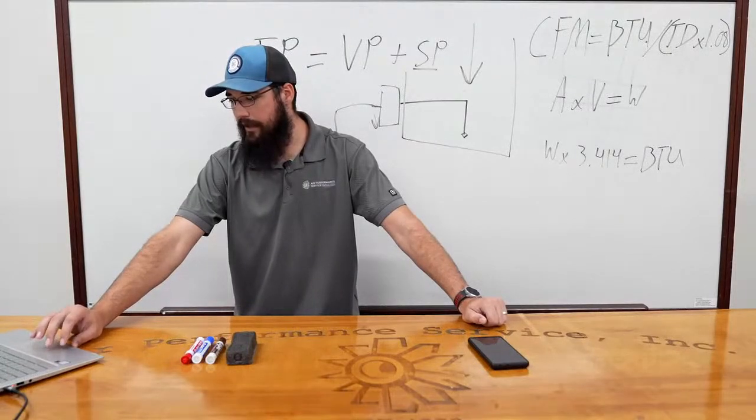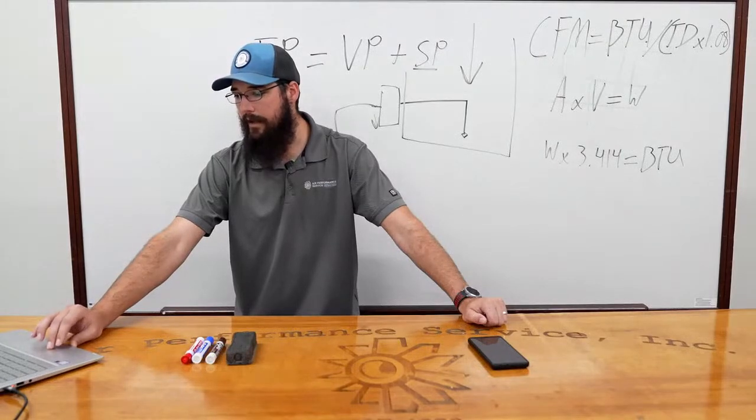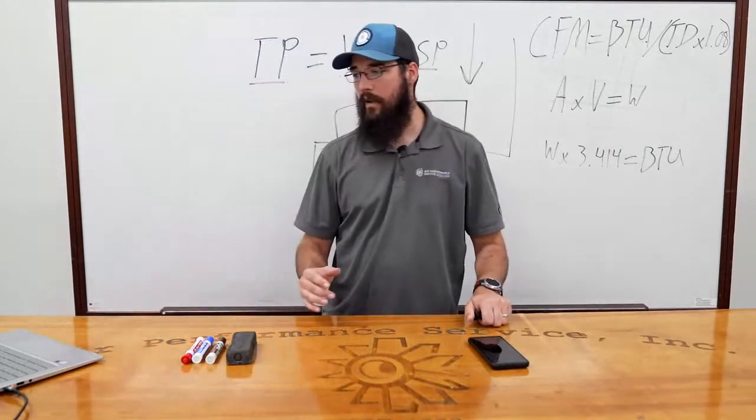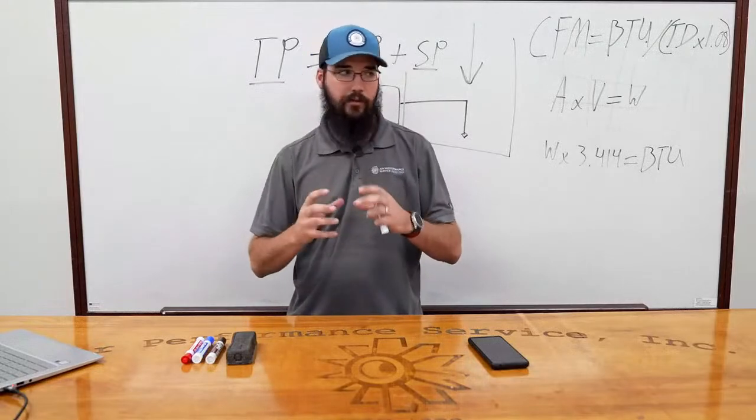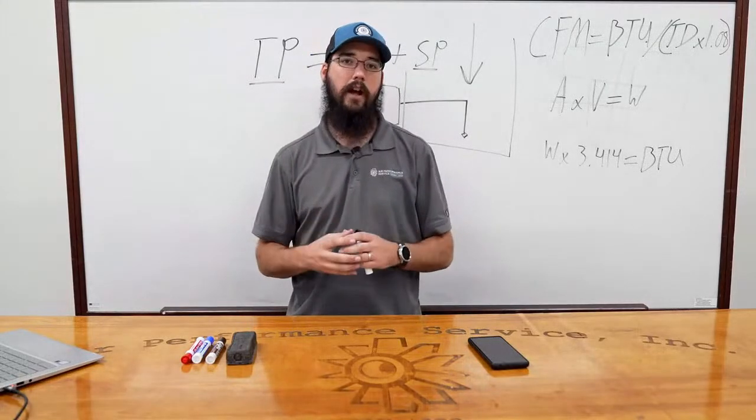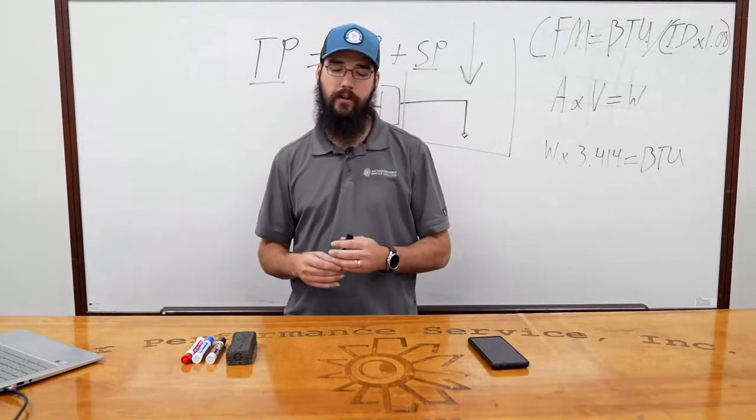And if we increase our diameter here, you'll see that the increase is happening at the larger pulley as well. So you can use a tool like this to help you identify how much you thread that adjustable pulley in or out. And that's really what you're trying to hone in on.